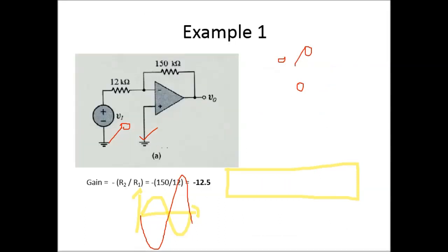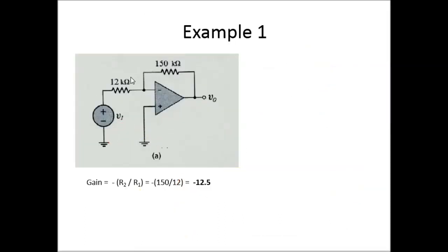Let me wipe this off. So this is obviously a direct representation of an inverting amplifier. Your non-inverting input is grounded, with the input signal and your feedback resistor. You can see that we do not label that this is R1, this is R2, so you need to know. My solution here is straightforward because I know this is an inverting amplifier. Let's say you are not sure.